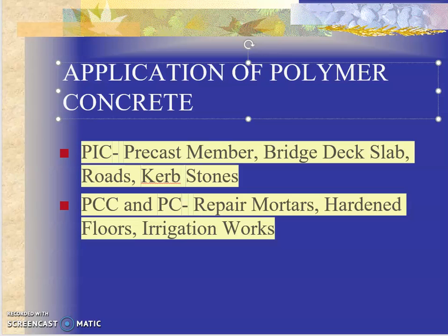Okay. When I spoke to some industry members, what they actually told me is these polymer concretes are used when the thickness of the element, let's say you are talking about a floor. If the floor thickness is, let's say, around 15 centimeters, now this polymer concrete will not be used for the entire 15 centimeters. It will be a small layer on top of that flooring. The topmost maybe 2 inches or 3 inches will be made out of polymer concrete. So it will be an extremely tough type of concrete.